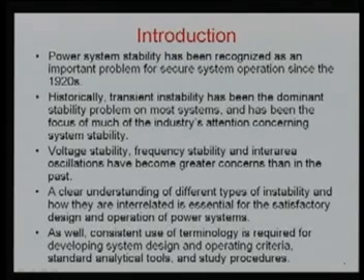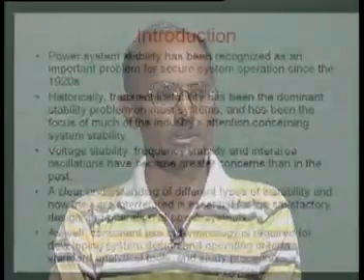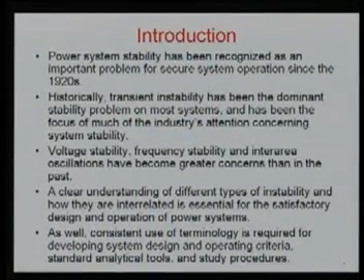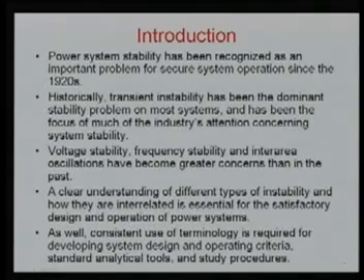In early days, people only recognized the instability phenomenon as transient instability. So they concerned themselves with analysis, mitigation and other related issues only for transient instability. But due to increased interconnections and stressed power systems, that is, systems that keep on loading and interconnecting, voltage stability as well as frequency stability, along with inter-area oscillations, have become a greater concern than in the past. It is due to more and more interconnections and a highly loaded and complex power system that voltage stability, frequency stability and inter-area oscillations are also very important, and that's why we have to go for the various stability analyses.